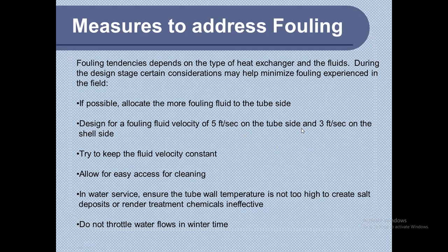So tube side is 5 feet per second. On the shell side, we have 3 feet per second. So try to keep the fluid velocity constant as much as possible and allow easy access to cleaning.